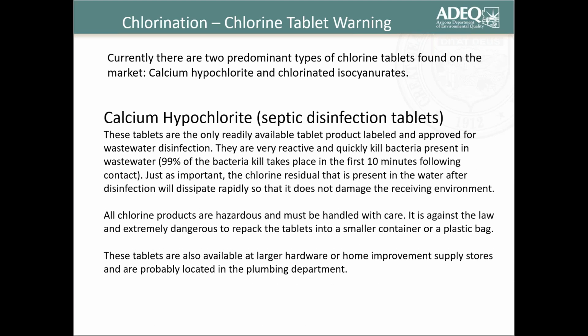The calcium hypochlorite, which I put in parentheses, septic disinfection tablets, because in some places that's what they're called. That's very misleading, but nevertheless, that's the label. So these tablets are the only readily available tablet product labeled and approved for wastewater disinfection.